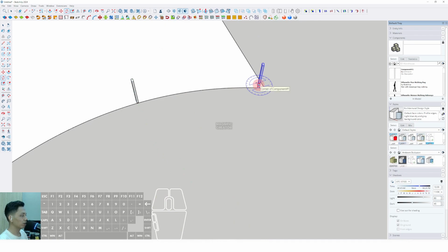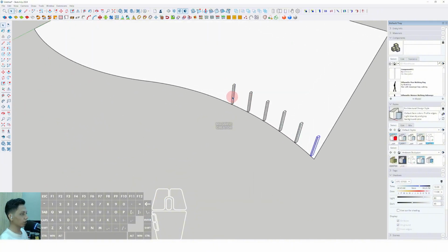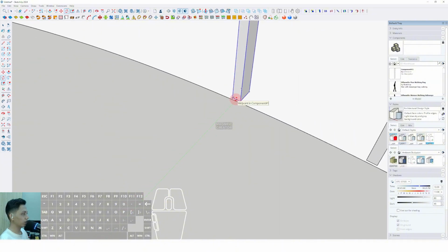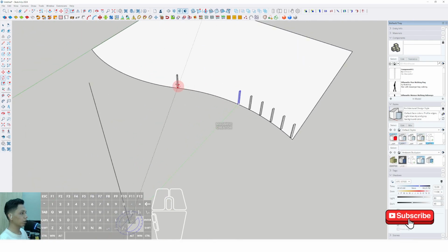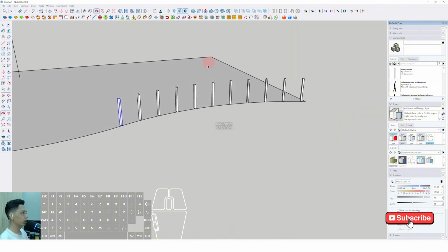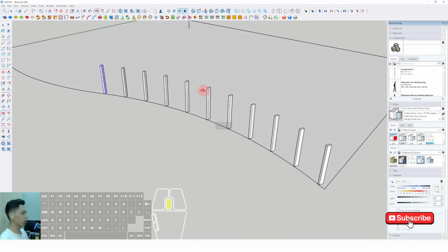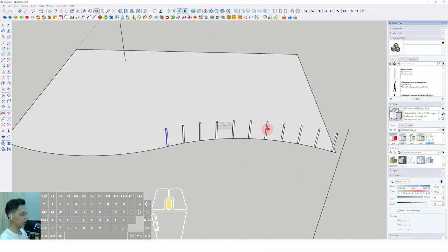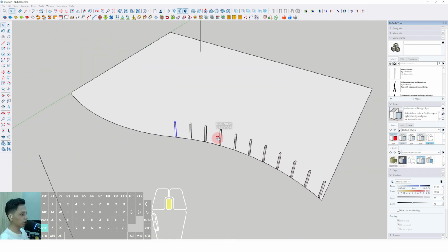Click, and then we can type 5 slash and enter. Okay, and also for this one we can select rotate, press Ctrl and click from this endpoint, and we can click this midpoint, and we can place it to this end position. Click and then we can type 5 slash and enter also. Okay, and we can get the clean vertical frame facade to make the glazing wall of this commercial building.